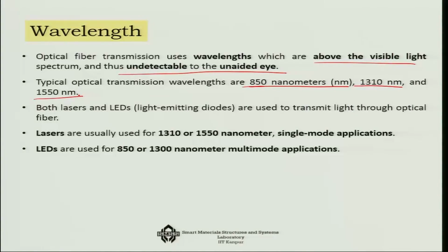Both lasers and LEDs, the light emitting diodes, are used to transmit light through the optical fiber. Lasers are usually used for 1310 and 1550 nanometer in single mode applications, whereas LEDs are used for 850 or 1300 nanometer in multi-mode applications. LEDs are slightly cheaper, but lasers are more expensive, and they are used for single mode applications for the highest quality data rate.